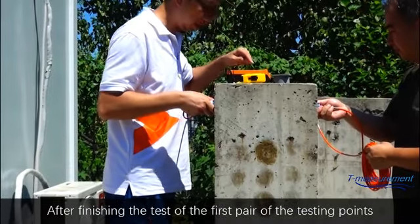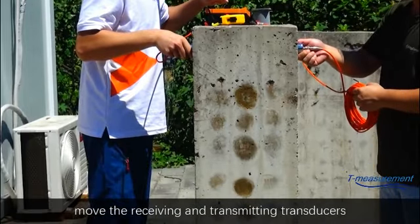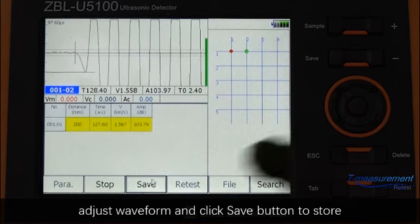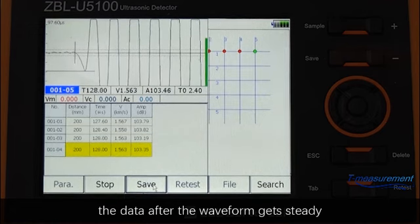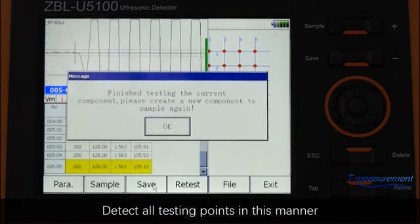After finishing the test of the first pair of testing points, move the receiving and transmitting transducers to the second pair of testing points, adjust the waveform and click the Save button to store the data after the waveform gets steady. Detect all testing points in this manner.